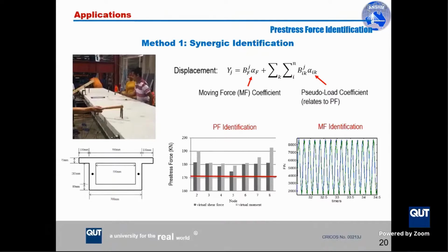By inverse calculations, we measure the displacement and do the inverse calculation, and we can identify the moving force and the prestress force. The experimental results show here a good prediction of prestress force as well as a well-matching moving force.